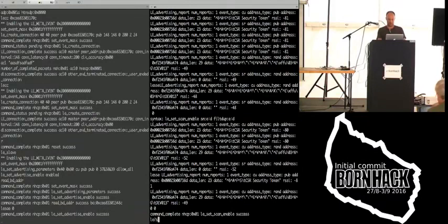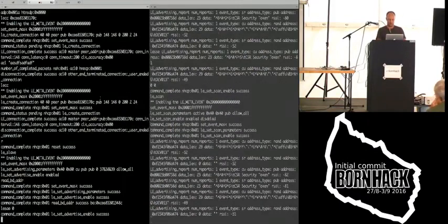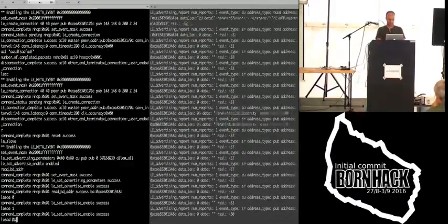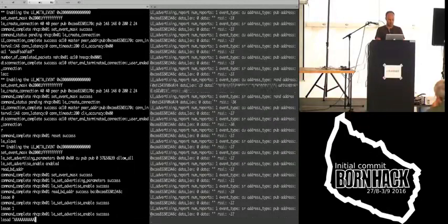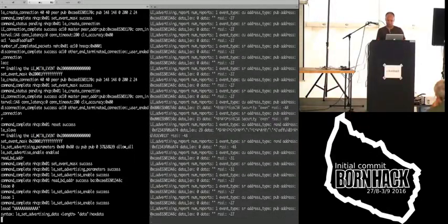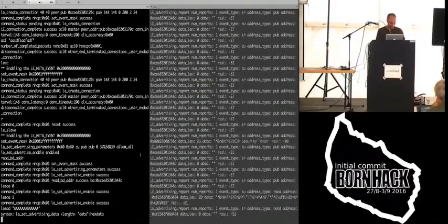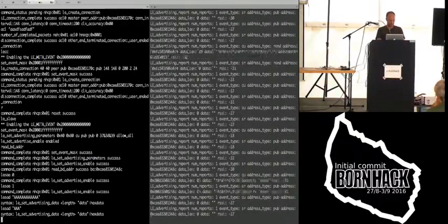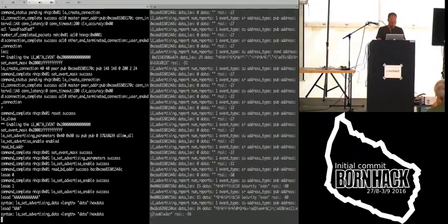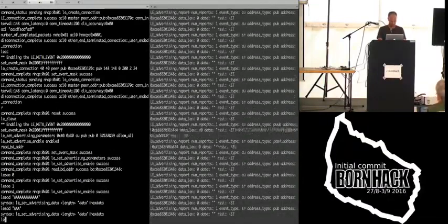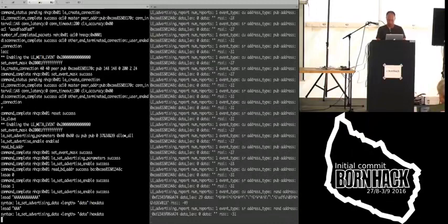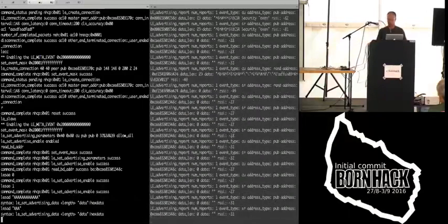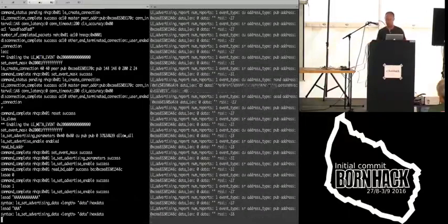So if I do this scanning again, and I start scanning over here, and then I can try to change the data. I just send out a bunch of A's, and these should show up in the data. Okay, there's some bug here. I don't know with the tool. Anyway, we can see that the signal strength from the two phone devices is like minus 30 dBm. So this is reasonably good.